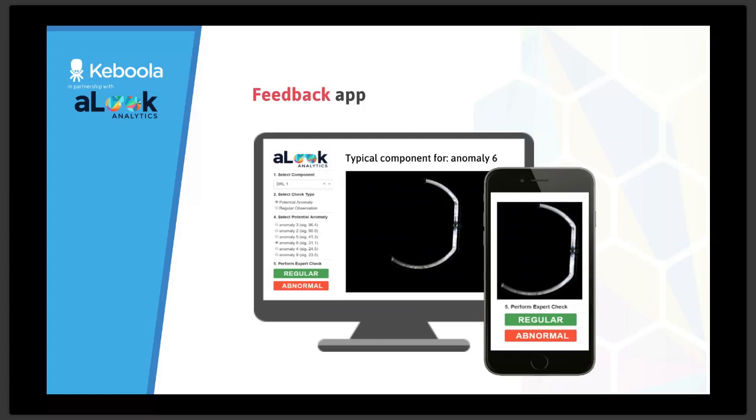The reason why we ask here is that you might have an anomaly that is also a defect, but at the same time, there might be types of anomalies that are different from the rest of the OK pieces, but they are still OK. So it's neither a functional nor a decorative flaw in the image, and you can still consider the component to be OK. Once you have this implemented and it's running automatically on the production line, this application is spotting new types of anomalies unseen before, and is automatically asking the expert for their opinion.